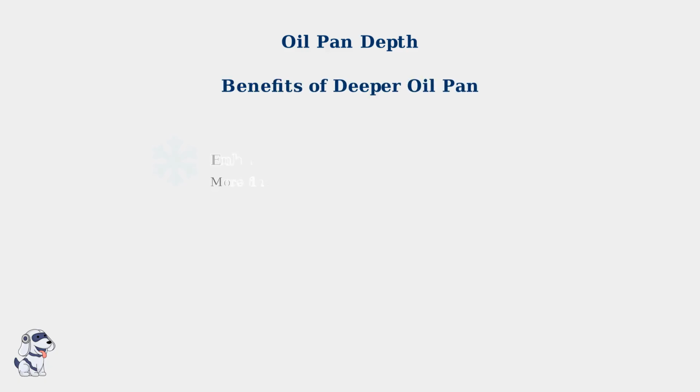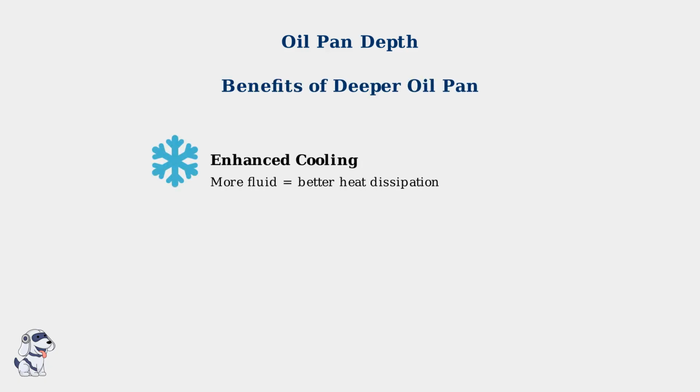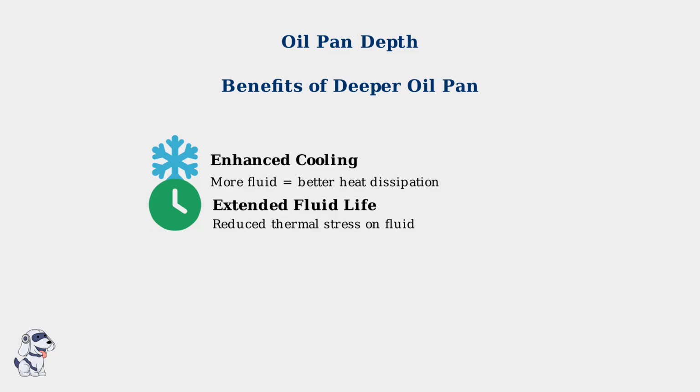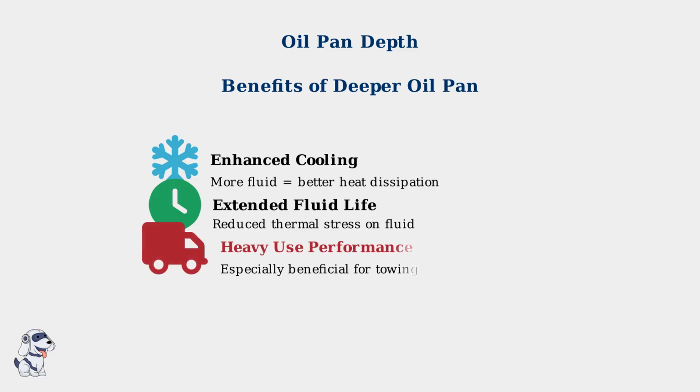The deeper oil pan provides three key advantages. First, enhanced cooling capability. More transmission fluid means better heat dissipation, keeping operating temperatures lower during demanding conditions. Second, extended fluid life. The additional fluid volume reduces thermal stress on the transmission fluid, helping it maintain its protective properties longer and extending service intervals. Third, improved performance under heavy use conditions.